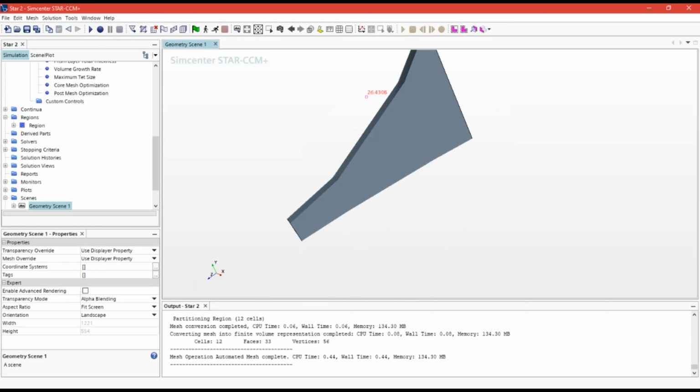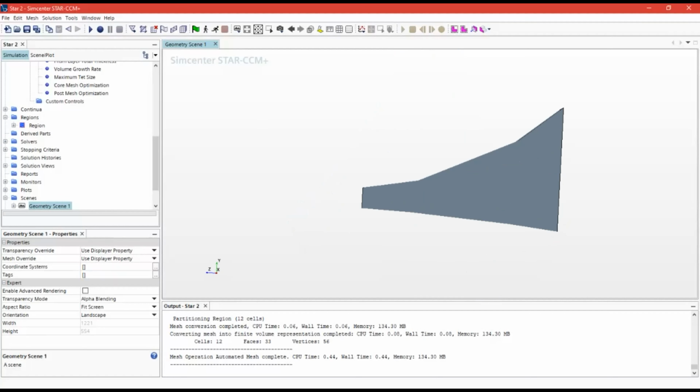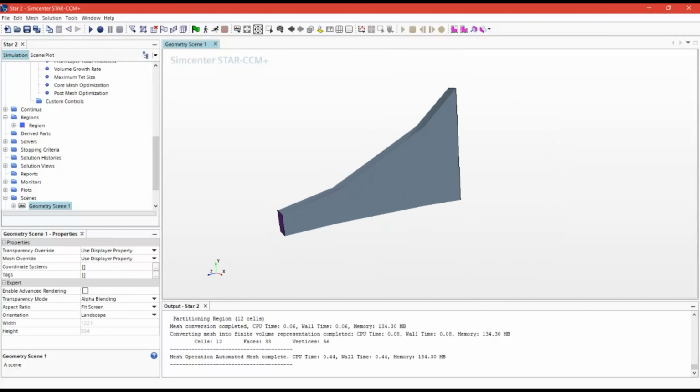The way that we want to select base size is, honestly, and I'm not making this up, just a guess and check game, meshing. Obviously, the finer your mesh is, the higher fidelity answer that you're going to get from your simulation, because you'll be modeling interactions on a smaller scale, which models real life more.